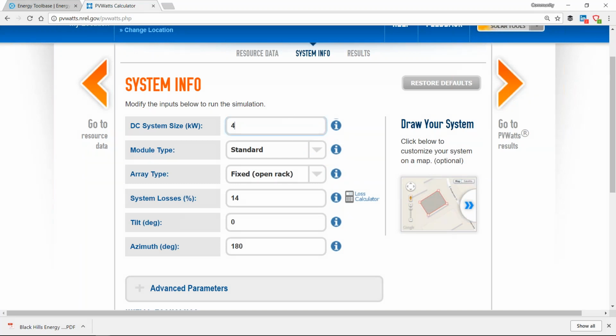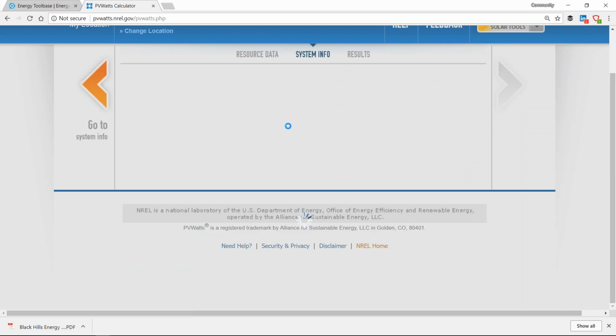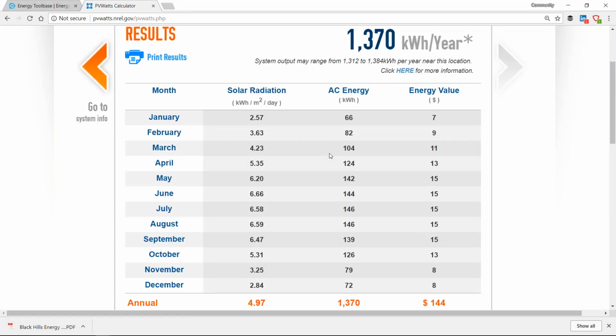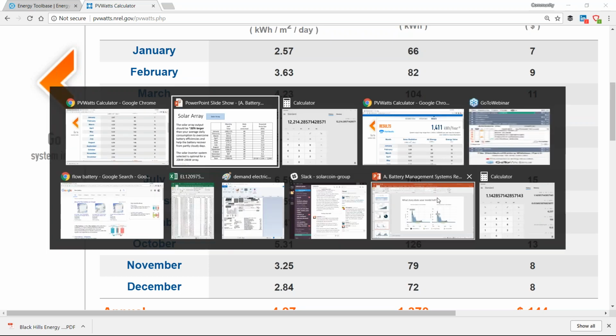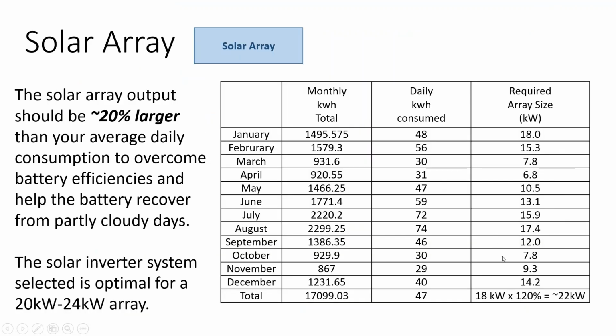let's go back and create a little scaler here. 1 kilowatt, and do roof mount, south facing, although that's not the only configuration. What I can see is that my production in the summertime is larger than my production in the wintertime, and my production in spring is also pretty good too. When I look at his monthly totals, I see that his consumption in the summertime is larger than his consumption in the wintertime, but actually in spring and in fall, his consumption goes down.